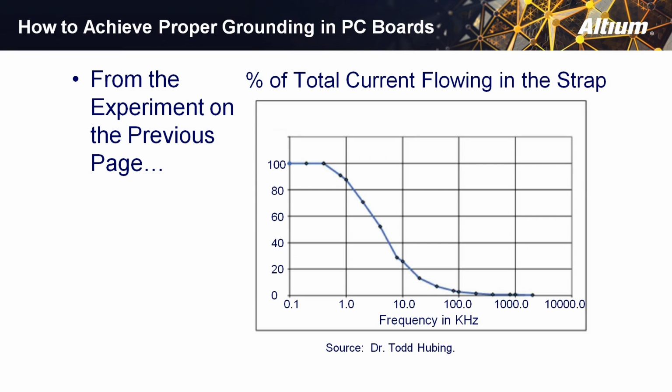That's how it works. All of the circuits you work with in the digital world today, regardless of clock frequency, are high frequency circuits because it's all about rise time. Rise time is what dominates frequency in digital circuits, not the clock frequency. I've seen many companies make the mistake of thinking, oh, we only clock at a few megahertz. We have nothing to worry about. They ignore rise time. They lay out simple 1 and 2 layer circuit boards that don't have adequate grounds, adequate return paths, and they get themselves into huge trouble as a result of it.